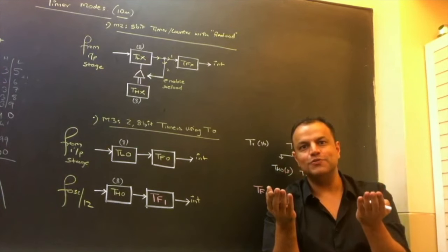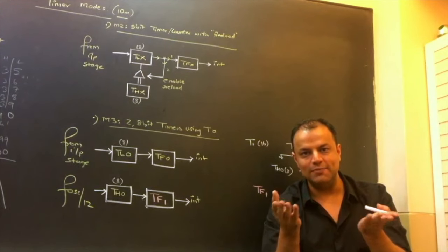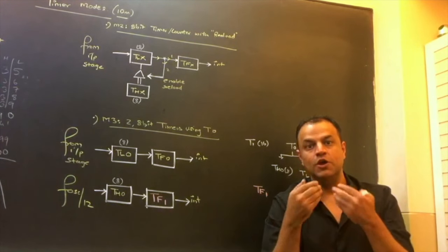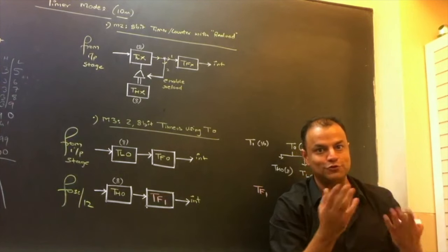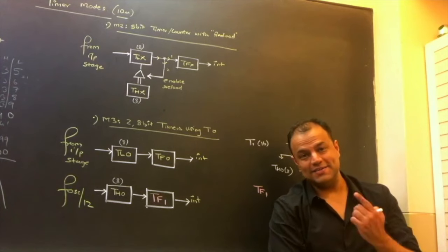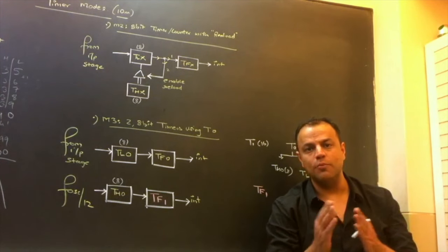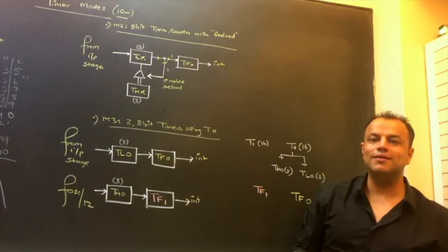To make 2 copies of the count, it has to be an 8-bit count, because your whole register is 2 8-bit registers giving you space of 16 bits. If your count itself was 16 bits, both your registers are occupied in holding the count. Where will you store the backup copy? Please tell me, did you understand this? So that is why it's an 8-bit mode, so that you can make 2 copies of your count, one for counting, one for reloading. So suppose your count is an 8-bit number like 35.